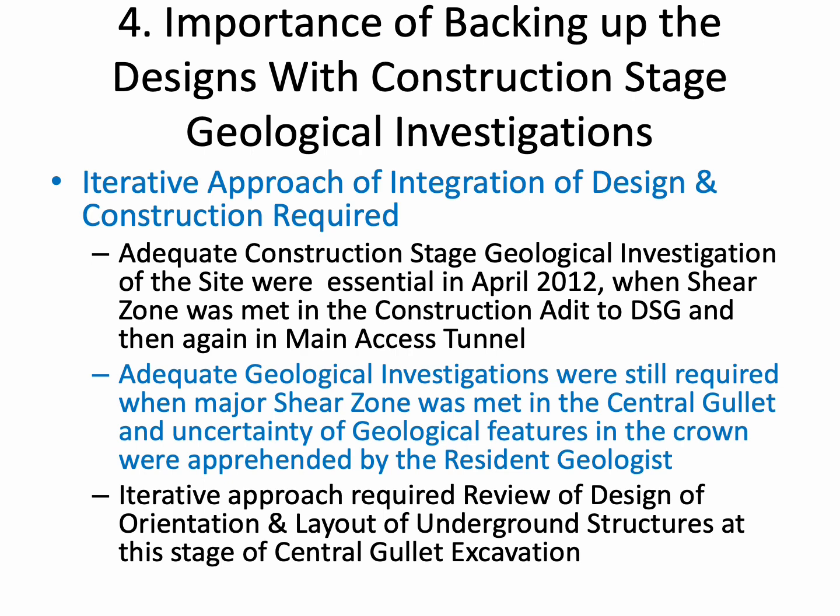Fourth point is the importance of backing up the designs with construction stage geological investigations. So we saw that the designs provided were based on fair to good geology as was inferred in 2010 investigations that were done prior to construction. So during the construction stage, whatever geology gets exposed, it becomes important to back up the designs with the construction stage geological investigations. An iterative approach of integration of design and construction thus is required.